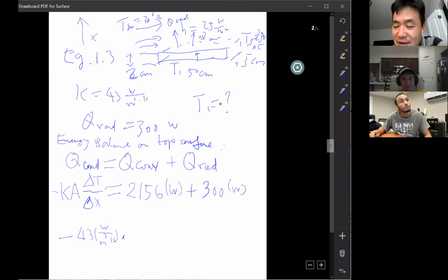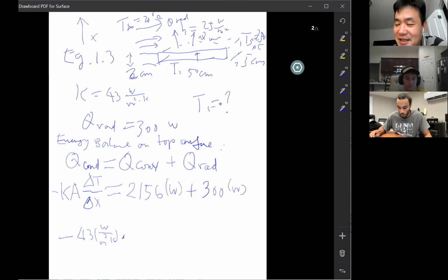See, homework 1.7, the reason it's difficult: it's a cylinder. Heat goes through the cylinder wall, right? So the area that heat flow goes through is not constant. Remember, how do we calculate the heat transfer rate in conduction? With the cylindrical coordinates, the area is not constant. We have an example problem, right?